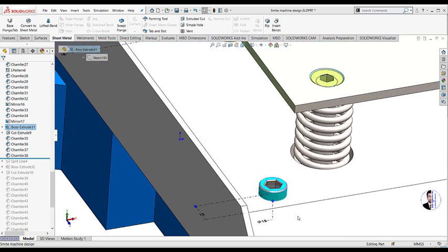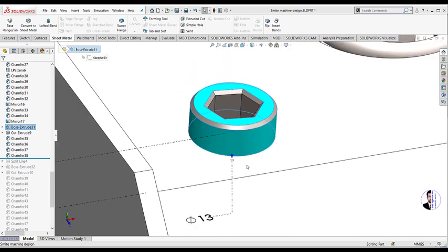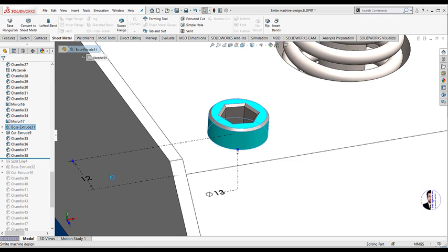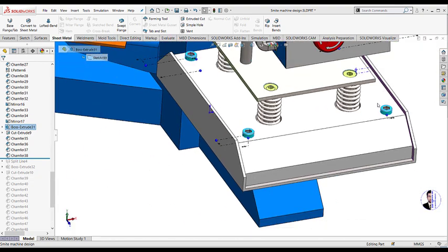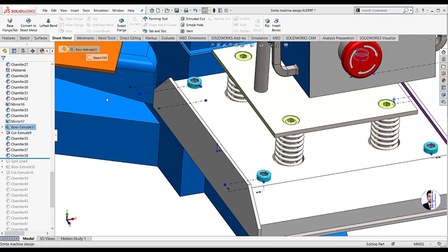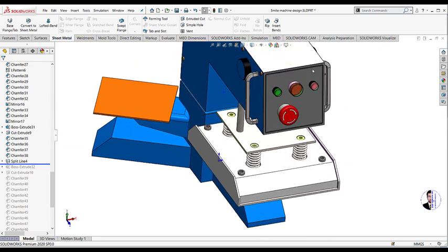Again create the main heat press plate nut, which is basically 30 millimeter and 20 millimeter distance. There are 4 linear patterns here. Now looks good. Again split line. Create the nameplate, Smith heat machine.